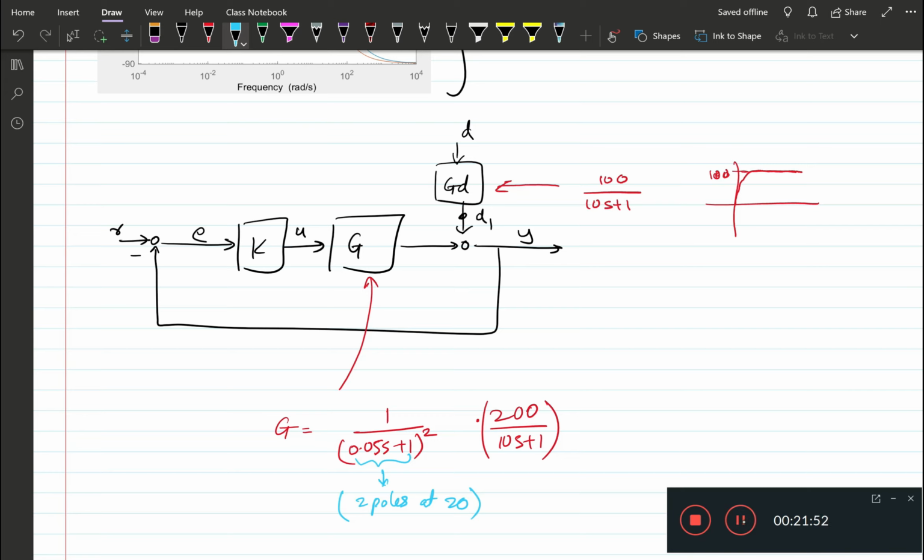So this G is a third order system, and because this T1 is very quickly moving towards 100 and we want the output Y for the disturbance rejection requirements to stay within -1 and 1, so in this case less than 1, in order to maintain these requirements, the controller must act extremely quickly to have this input cancel this T1, which is moving rapidly to 100.